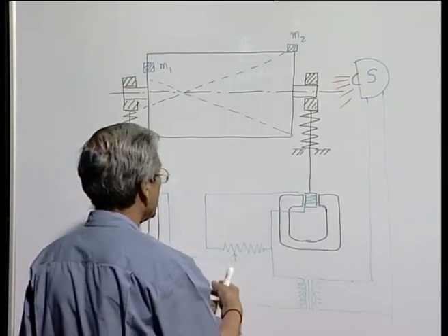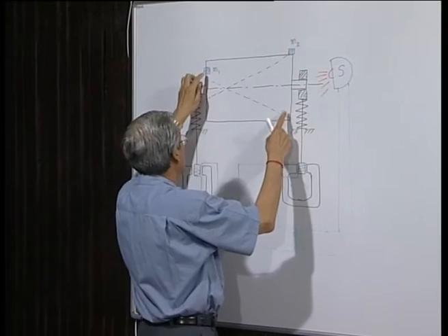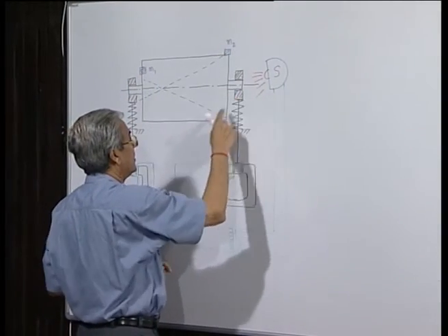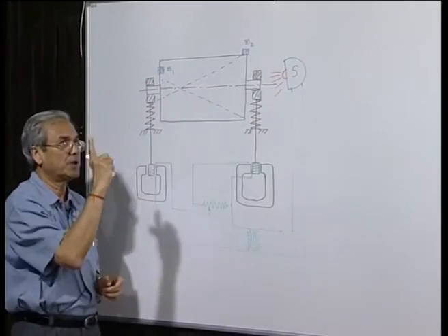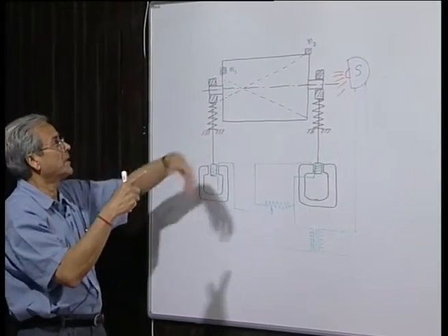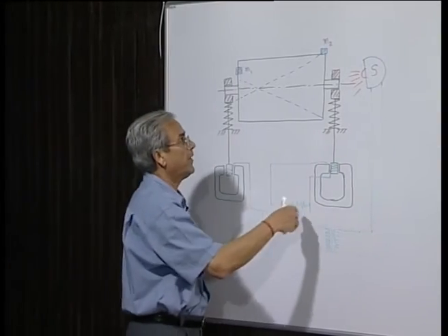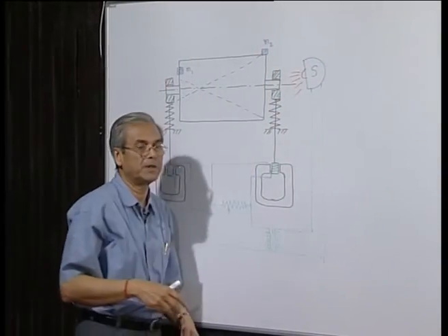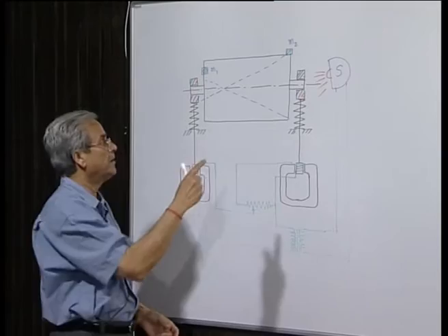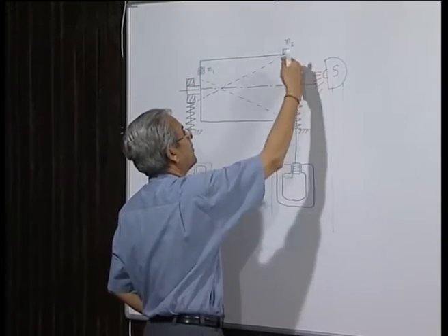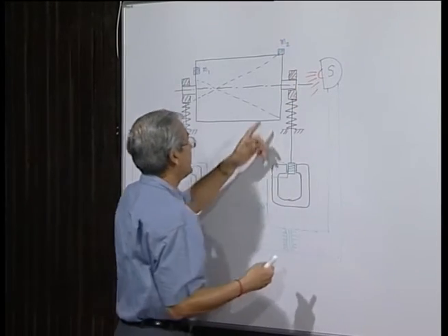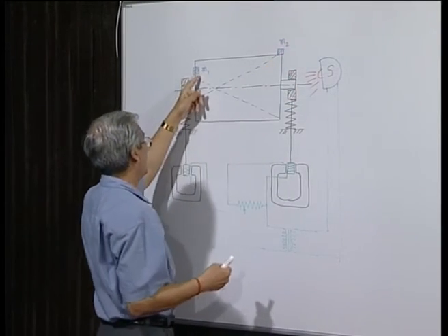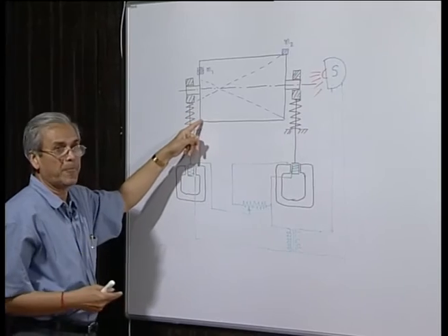It is arranged in such a way that when this is at the top position in its vibration, it flashes. So, you can see the angular position if it rotates at reasonably high speed. You can see the marking, there will generally be a protractor kind of arrangement, which will show you the angular position when this is at the highest or where M1 is the lowest.